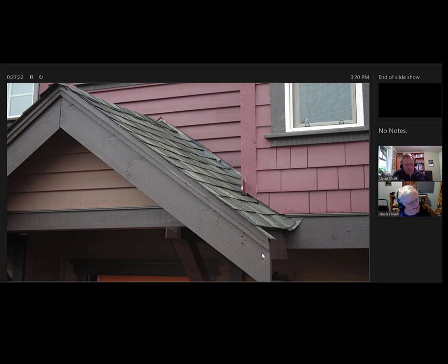I can't think of anything. I think we covered it. We didn't talk about the edge flashing that shows in this picture. Yeah, that drip edge is now required, along with on the fascia, it's required as well. But that metal should be what caps that barge rafter, really. And here they've actually done a pretty nice job. They've gone all the way down to the base of the barge rafter, exactly. And then the shingles are just decorative on top. Yeah, that's kind of nicely done.